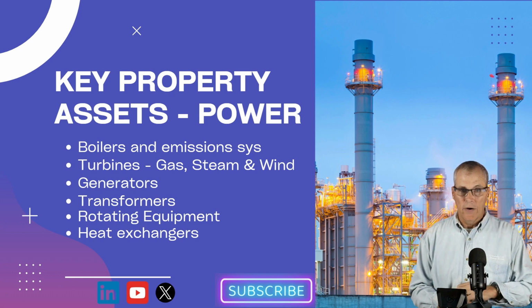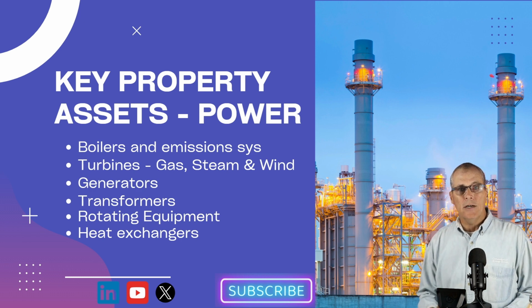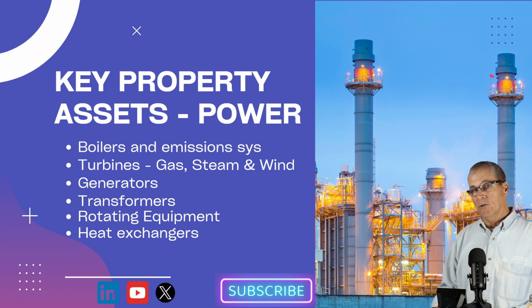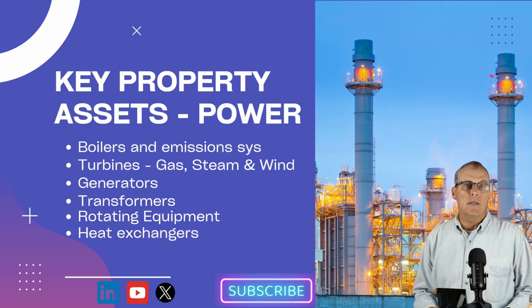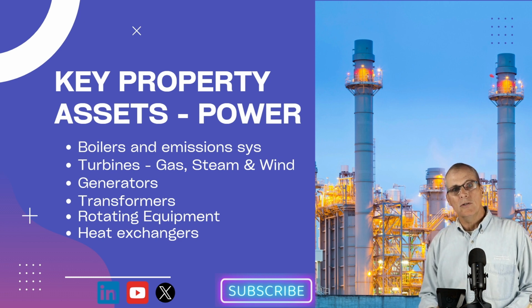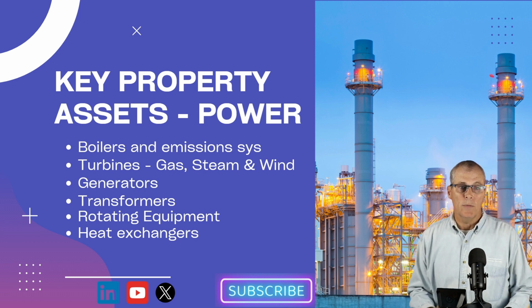Generators, these are very heavy, very large, and depending on how they're cooled, they can add hazards. You can cool them with air, hydrogen, or water, and they all bring along their own set of risks. Without a generator, a power plant's pretty much useless. Same with their transformers. The generator step-up transformers, just one more in that bottleneck that are very likely to cause a plant-wide shutdown. Transformers may not be your largest loss in the plant, property damage-wise, but they can shut you down for a very long time. 12 to 18 months, and even now maybe up to 24, depending on the configuration of your transformers.